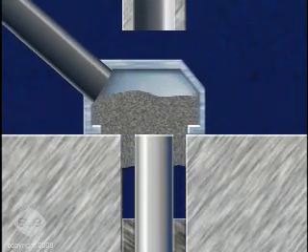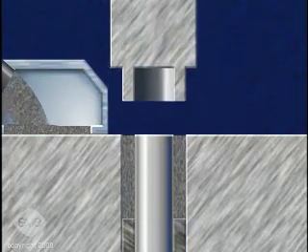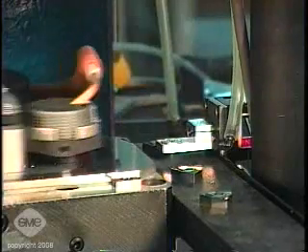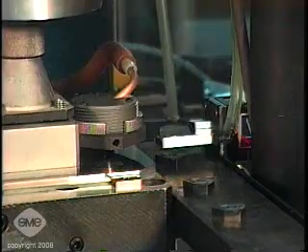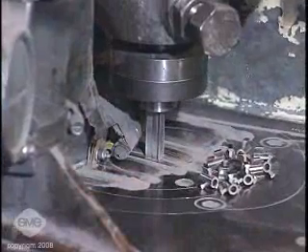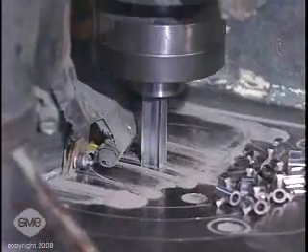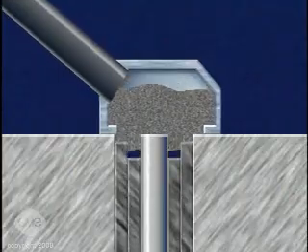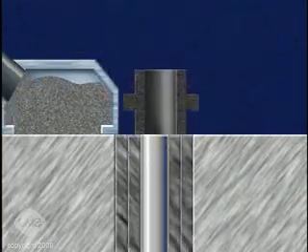The part is then ejected by the wiping action of the powder feed chute, which also wipes powder for the next piece into the die. Ejection from the press can also be accomplished using automated handling equipment. The density of pressed powder tends to decrease along part height as the distance between the compacting punch and die increases. To produce more uniform density, thick parts are compacted by a set of upper and lower punches.